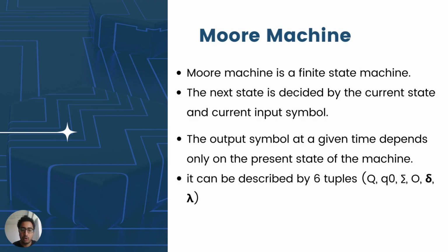Let's discuss the Moore machine. A Moore machine is a finite state machine whose output values are determined only by its current state. This is in contrast to a Mealy machine, whose output values are determined both by its current state and by the values of its input. Like other finite state machines, in Moore machines the input typically influences the next state. Thus, the input may indirectly influence subsequent output.